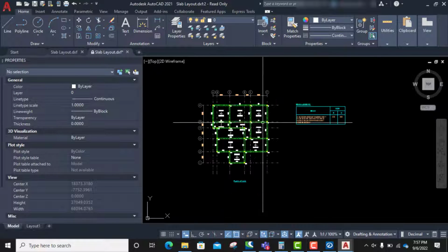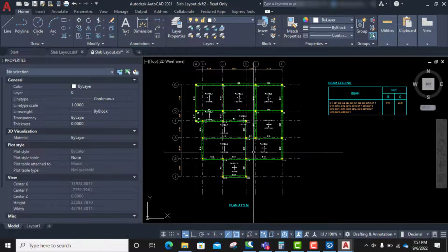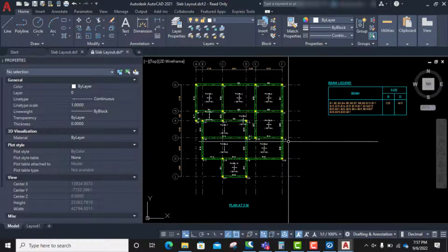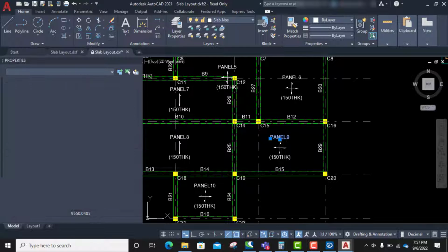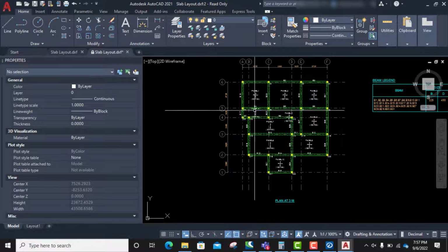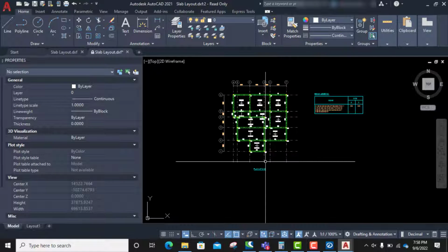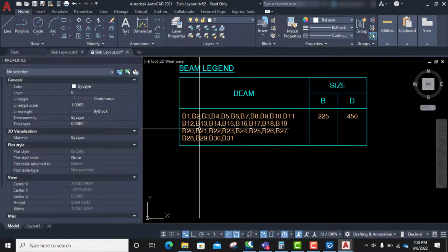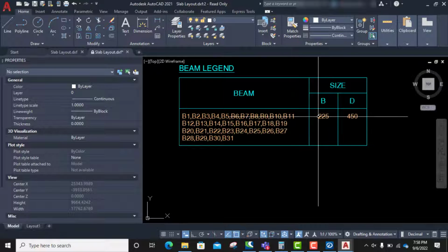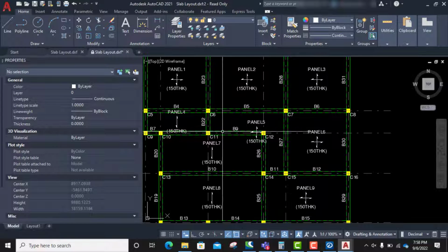You match properties. That's just what it means by cleaning up the drawing. Match properties. Make sure it has the normal text height, line weights and line types, and the normal scale. So the work is done already. These ones are the beam numberings and the beam dimensions. Yeah, that's that for this one. This is AutoCAD, if you do save it as an AutoCAD file.